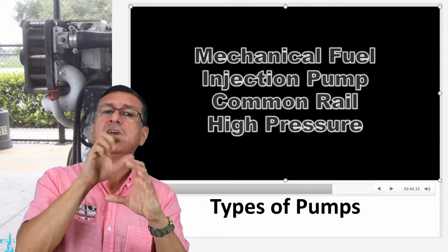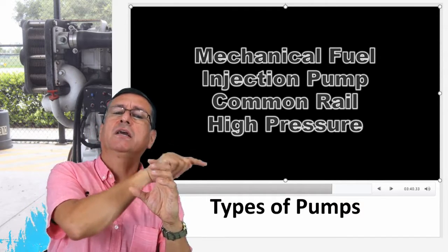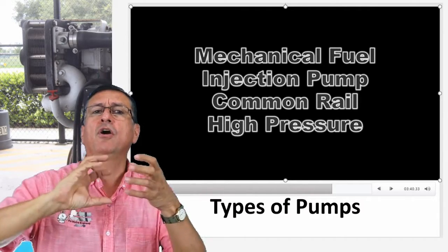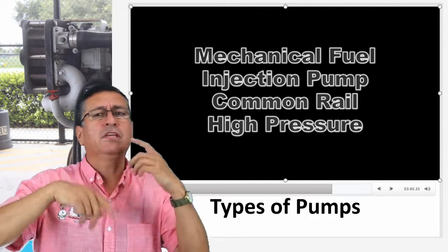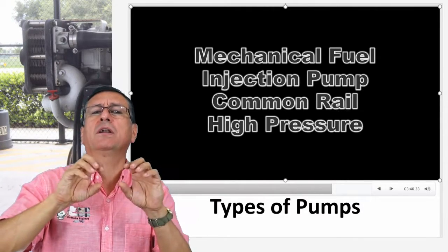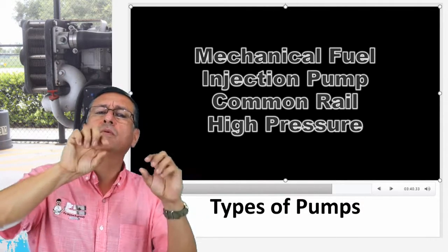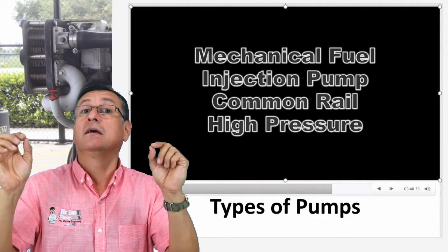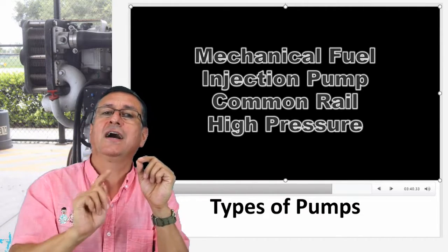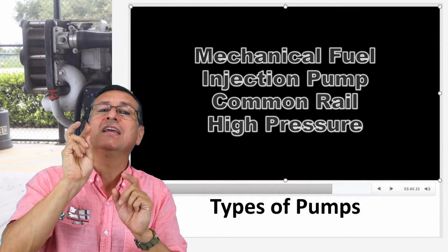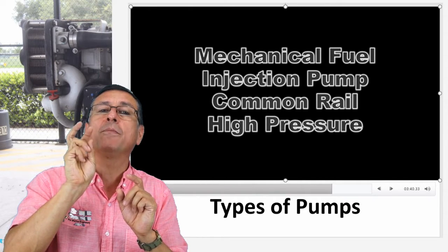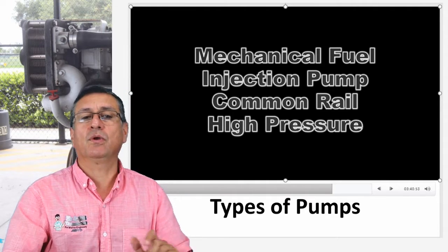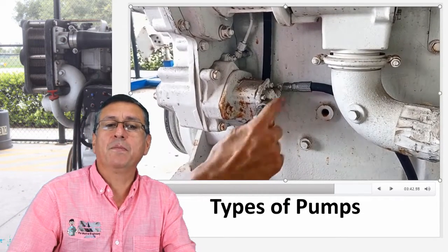The gear of that pump is connected with the gear of the cam and the gear of the crank. But in this particular case, you don't need to install that pump on time, because that pump is constantly producing power, and the fluid enters with high pressure in the common rail, and the common rail is constantly pressurized. But the fuel enters each injector only if the injector is open. The injector receives the signal from the computer, like this.